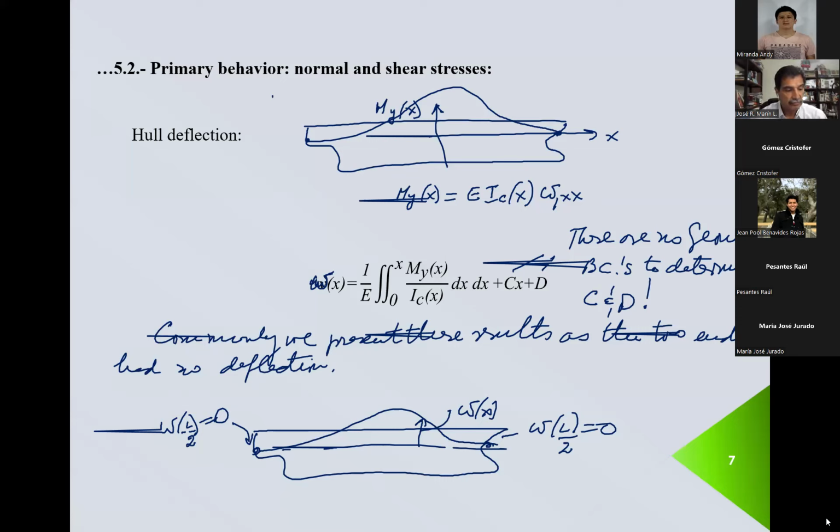The hull deforms, and because of this deformation, the points of support, or the bearings of the shafting system, move a lot. And because of these motions, the reactions on the supports change a good amount. Because of that, they suffered damage in the reduction gears, or there was even breakage of the shaft. And you can study that using this deflection curve of the hull.